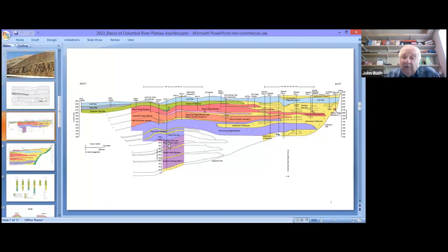Another piece of information, and I think it was used by the last modeler on the basin, is that there have been several numerical models which indicate that once you get below 1,000 feet, 1,200 feet, the fractures close, and the permeability, porosity, and aquifer productivity decrease with depth after that.